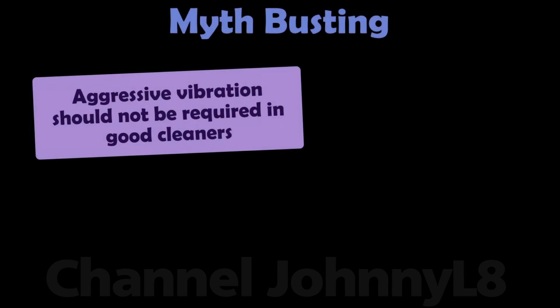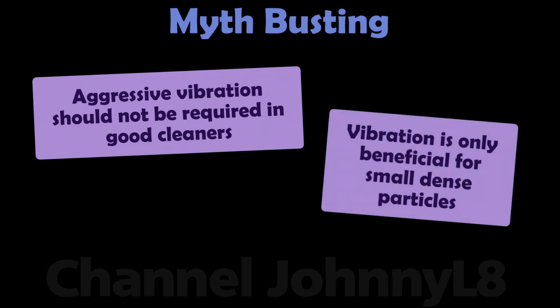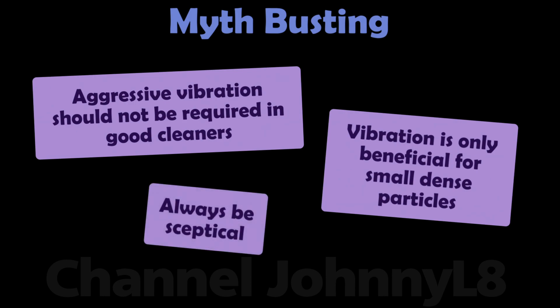The takeaway message from this video is that aggressive vibration should not be required in good cleaners. Vibration is only beneficial for small dense particles, and finally, to always be skeptical of YouTube demonstrations that aren't conducted to industry standards, no matter how convincing they might be.